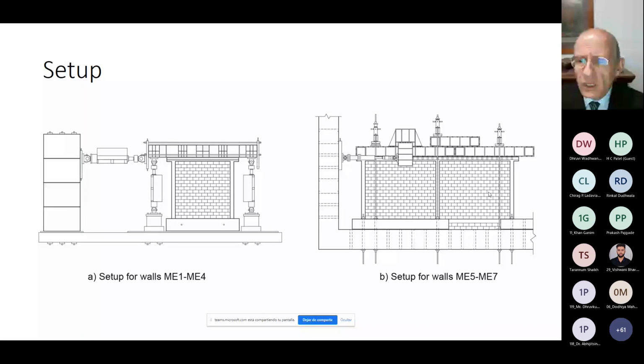And again, this is a very long beam, completely fastened. And we use this auxiliary beam here just to be sure that we are spreading the concentration as much as possible to the wall. Obviously there are some concentrations, but basically the idea with this very strong steel beam is that the force is applied here in one point, but is spread to the wall. Obviously, it's never uniform, but that's why we apply it in 3 points to be as uniform as possible.